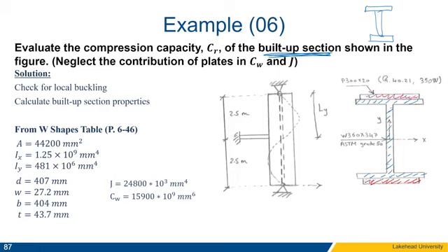This plate has a number of advantages, and it's important to understand those advantages. First, it will be increasing the inertia about the x-axis, obviously, and y, but mainly the x, of course. And accordingly, the Rx will be higher. So in that case, we are expecting the Cr to be higher.